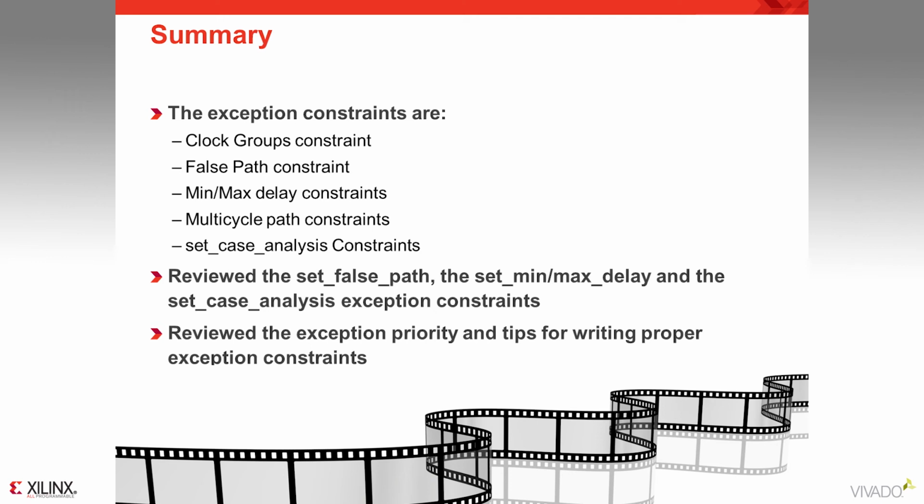In this session, we reviewed the various exception constraints and discussed in detail the false path constraints, the set min-max delay constraints, and the set case analysis constraints. We reviewed the exception priority and finally discussed a few tips while applying exception constraints.